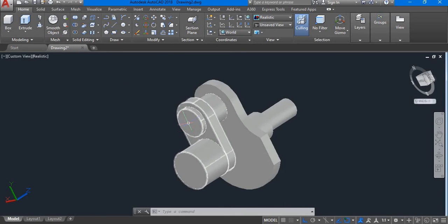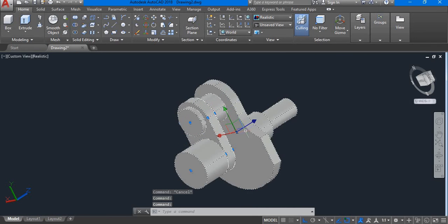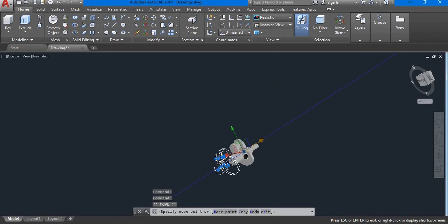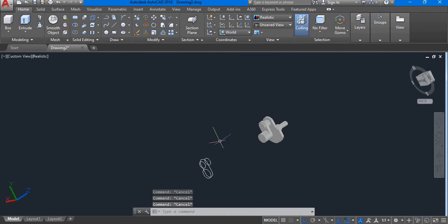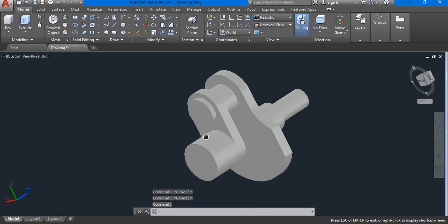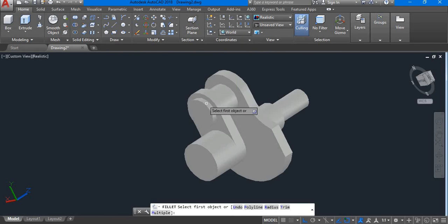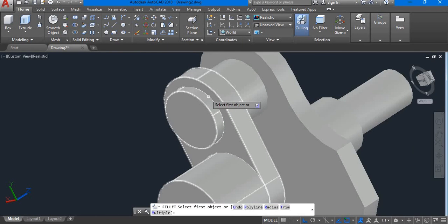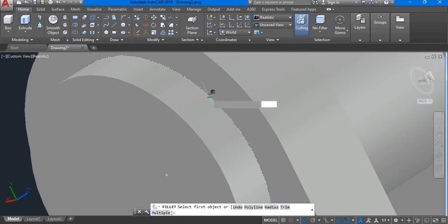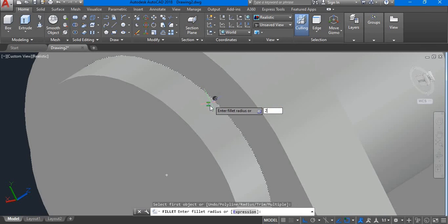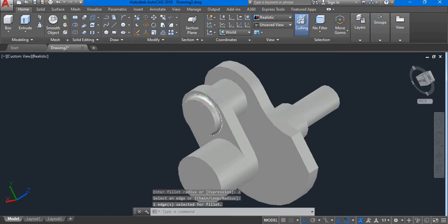Okay, we start from there. That's the fillet command. First of all we would make sure that we move this. Let's click and left click here. Let's move it to another part, so we separate it from the construction lines and circles. So the fillet command, let's click there, specify here. This is where I am clicking, and we type 2, enter, and enter command again. So we are done with that.